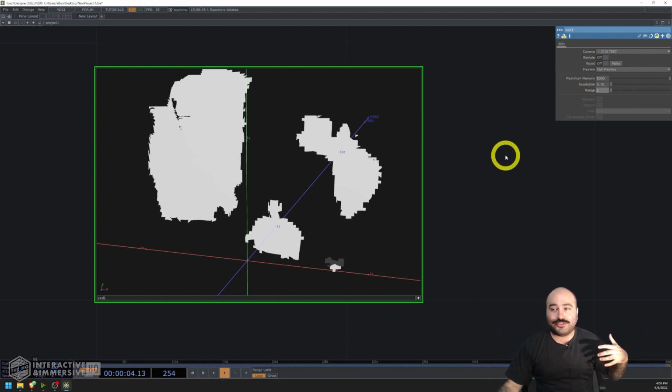I'm going to turn this down to 2, which is kind of the minimum that it lets you go down to. Now, if I was outside and maybe scanning a house or a car or something like that, or just an environment, I might want to keep this higher, maybe around 10 meters as my focal length, or maybe even up to something like 18 or 20 meters. Now, in this case, I'm going to bring this back down to 2.